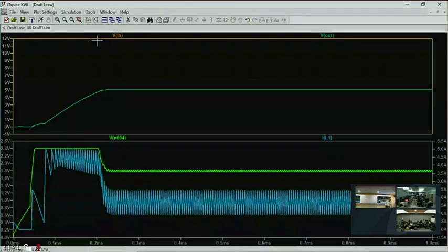One thing about the startup transient analysis is that sometimes it's the only way of seeing the slope compensation function of a controller. Now, I drew here just a triangular wave for the slope compensation function. In fact, we use proprietary slope compensation functions. They're not triangular waves. We can do better than just a triangular wave. The IC designer who thinks of this proprietary function to build into his IC is enthralled with it when he writes the data sheet, and he wants you to like it, he wants you to buy it, but he sure doesn't want to tell you what it is.